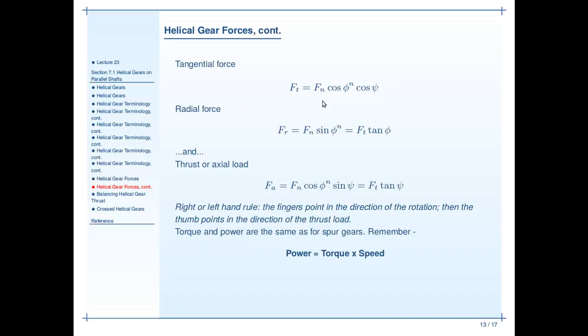We can calculate this in terms of the normal force, the normal pressure angle, and the helix angle. We can also relate these forces together looking at the transverse pressure angle. It's worth playing around with this a little bit, guys. Hopefully we'll get a chance to do a sample problem in class, but it is worth it to look at the forces as they resolve. Play around with your calculators a little bit. That's why you have them.